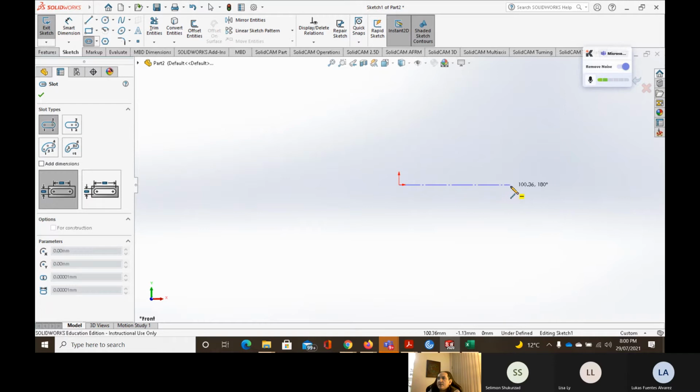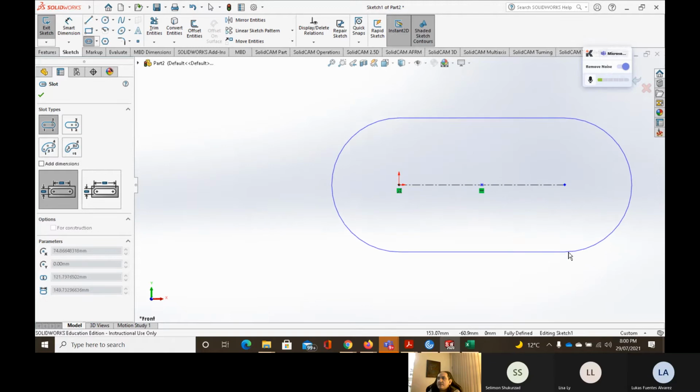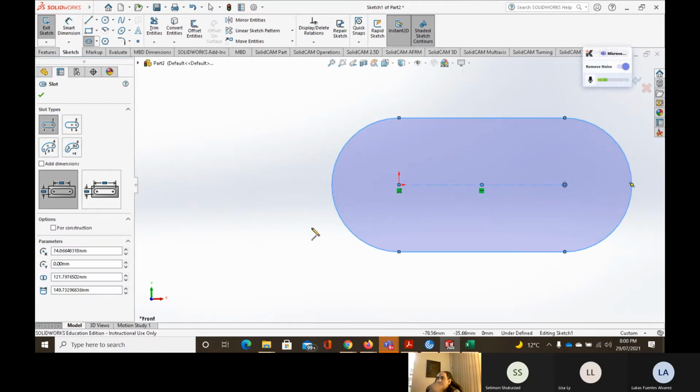So this side is meant to be 150, so I'm going to make it randomly 150, then I'm going to fix it myself. And the distance from here to here should be equal to 60. I can always fix that from here. This one, the height is 120 exactly. And the distance from center to center is 150 millimeters. So I have the shape now.